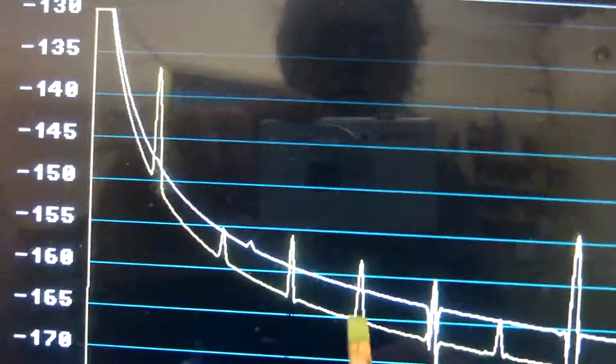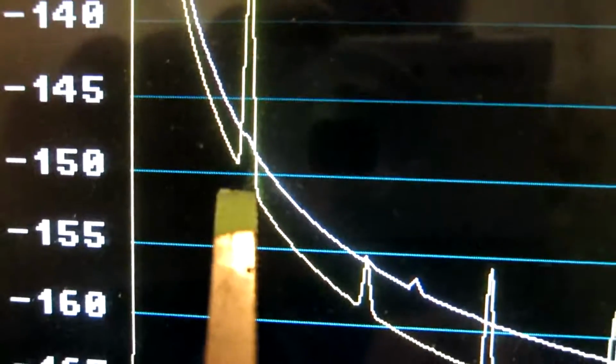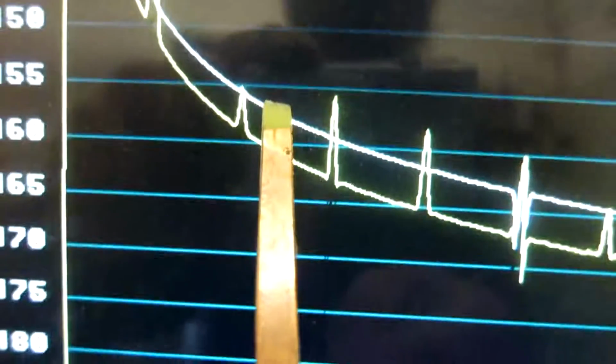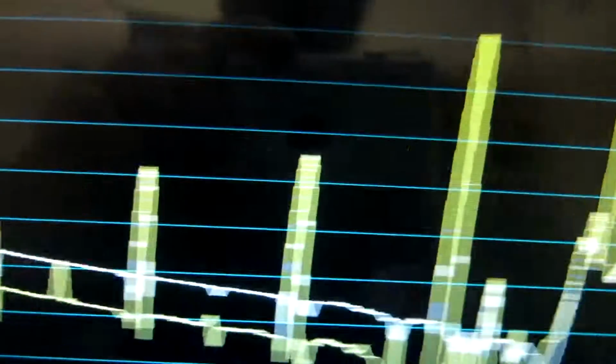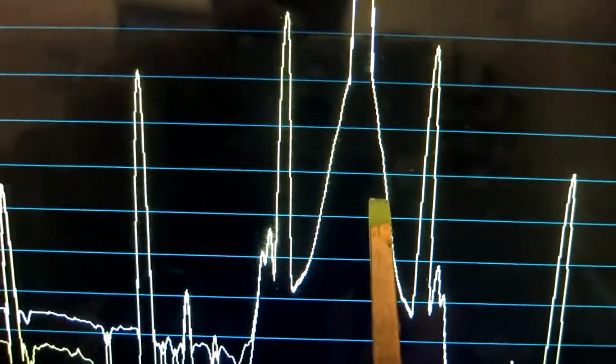The frequency scale, 200 Hz here. It's this peak, overtone from 50 Hz, so that is 200 Hz, 100 Hz, 50 Hz. Note that 50 Hz is almost only phase noise, phase modulation. 100 Hz, and this I don't know what it is. And then here is 700 Hz.